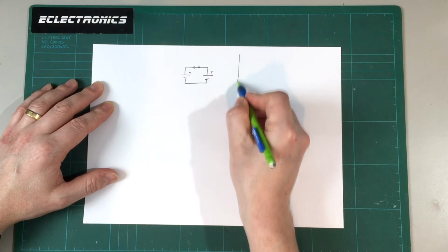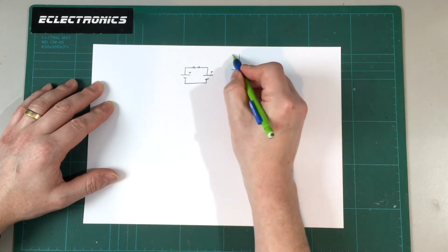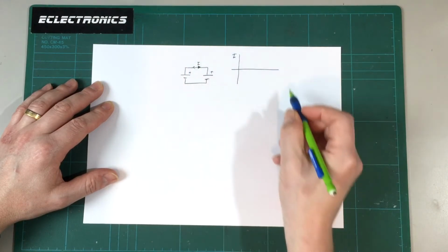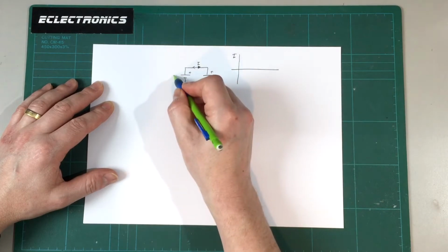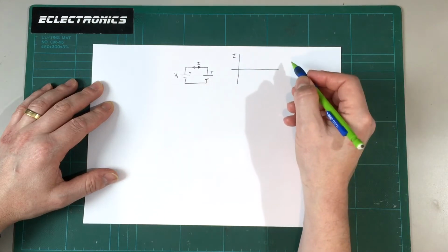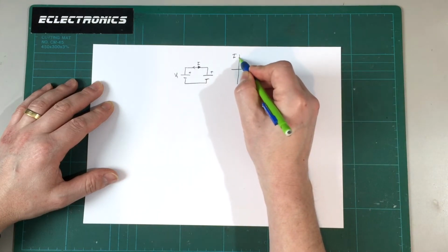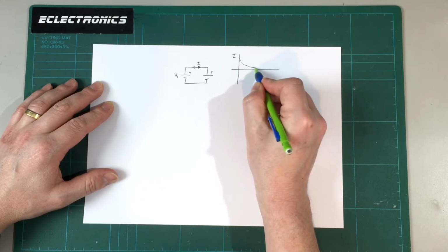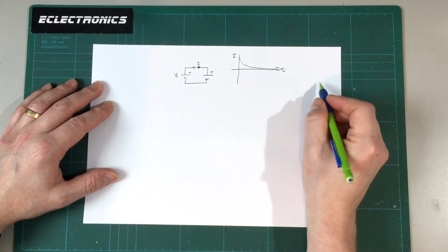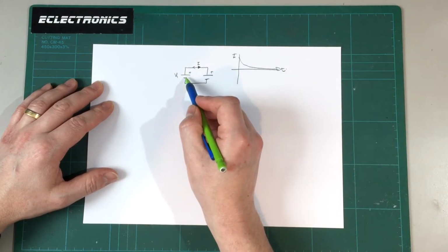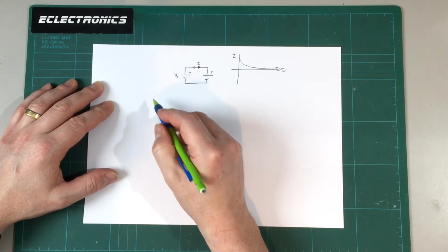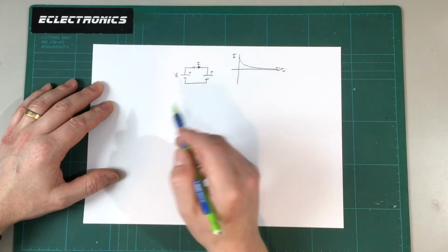So in terms of profile of current against time, if we define our current as I in this direction for the time being, it's going to start out at some value. Let's say cell 1 here, V1, was higher in charge to start with. Then we'd start out with a positive current. It would decay away fairly quickly, and it would drop down to almost zero levels as time went by. So if V1 had more charge in it, then the current would flow in that direction to redistribute the charge between the cells. So these would self-balance just by virtue of the fact they're connected in parallel, which is great.